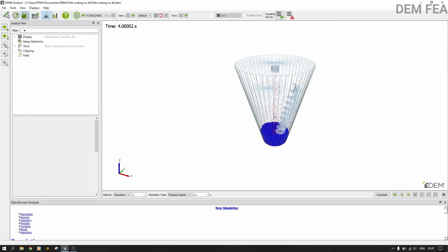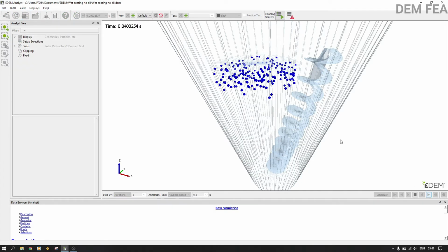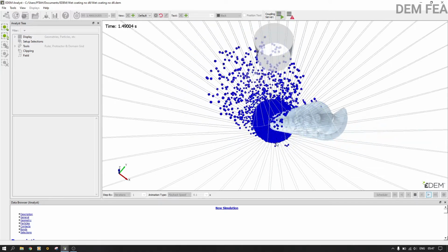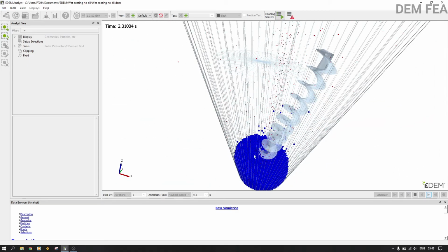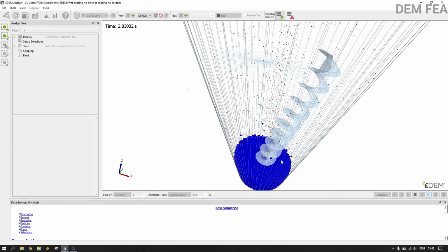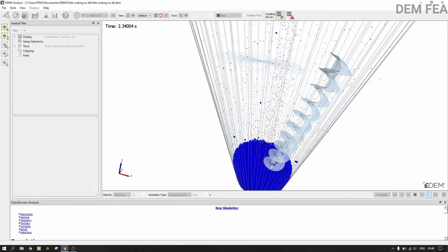did it again. So as you can see, this is the simulation only for 4 seconds. I colored in red the spray particles and also the other ones. I cut the particles, the regular particles, I just left them in blue. So let's see what is happening. As we can see, the spray particles, they are not getting absorbed and the other particles are not getting that cohesion aspect. They are just floating everywhere. So there is no mixing element. There is no wet mixing element.